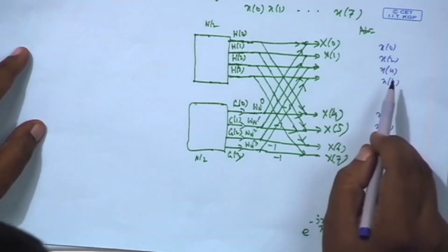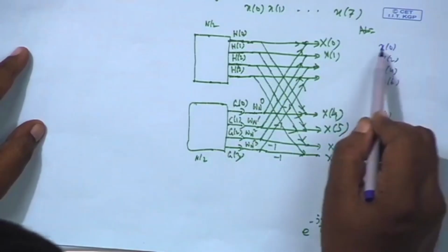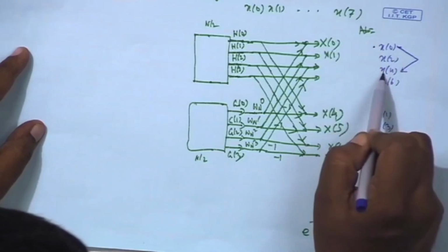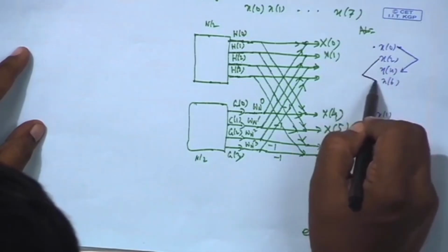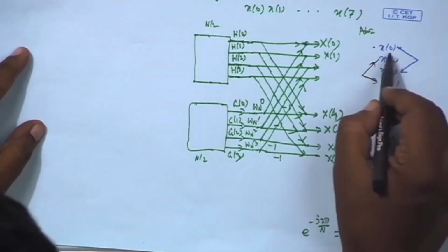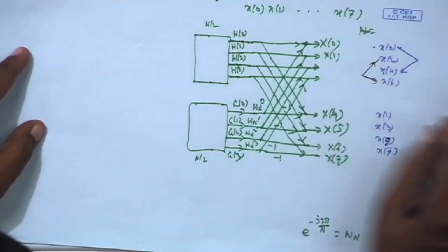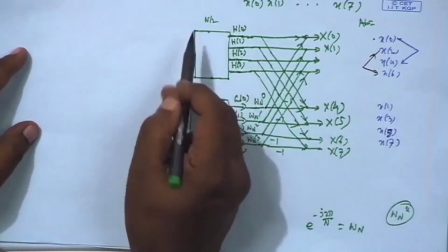Okay, on this, but this is a sequence. On this also I can apply the same philosophy. I can take out its even component, these two, the 0th term, second term, and odd components, these two. So, I will have a subsequence x 0 x 4 and another subsequence x 2 x 6. Okay, so, by the same token, this DFT can be obtained